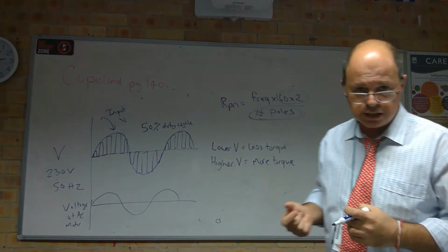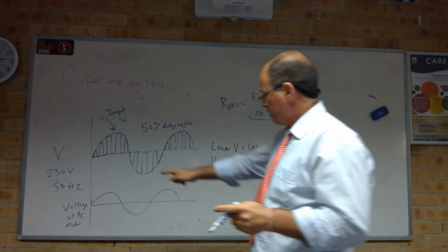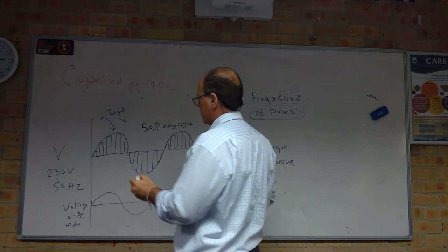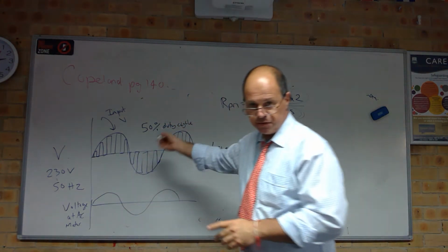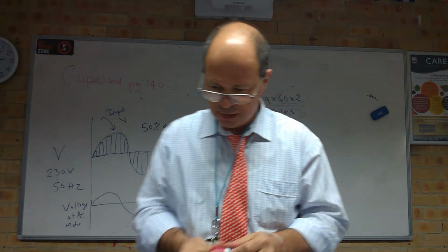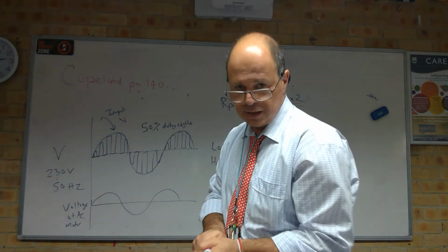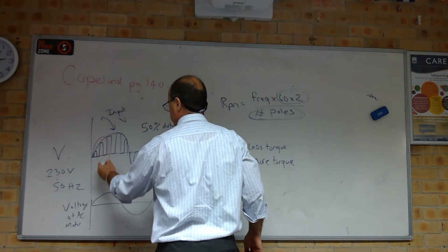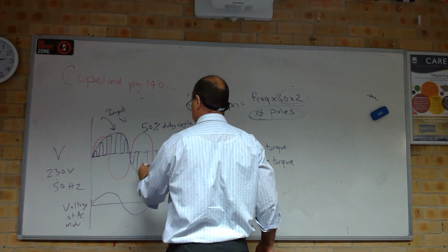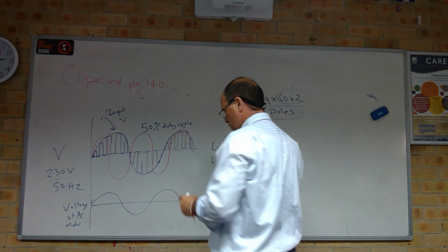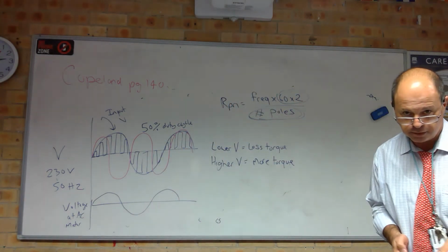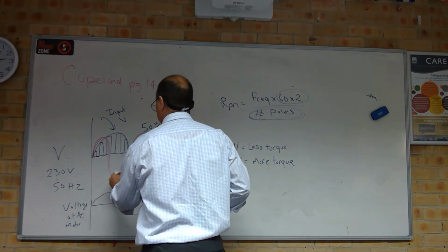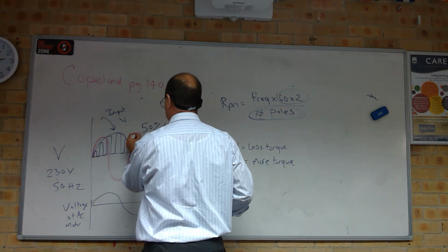We have electronics now that allows us to chop up that frequency that's coming in, okay? So instead of having a 50 hertz cycle coming in, we can play around electronically and chop that input. We could change it variably, infinitely, but we could, for example, double the frequency. So for every half cycle, we've got a full cycle.